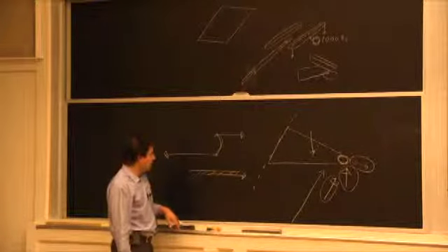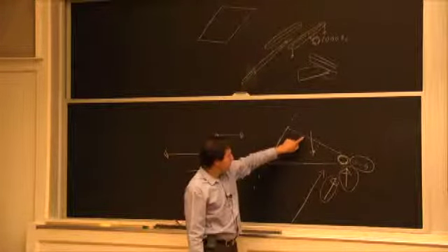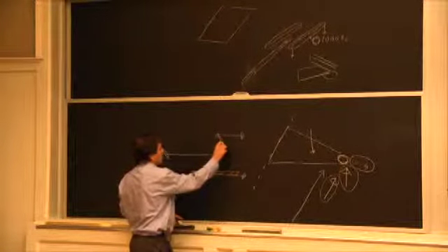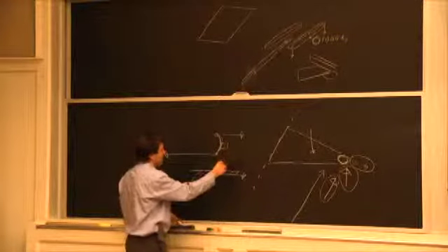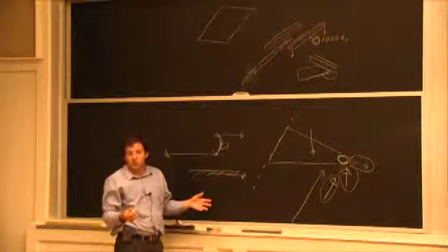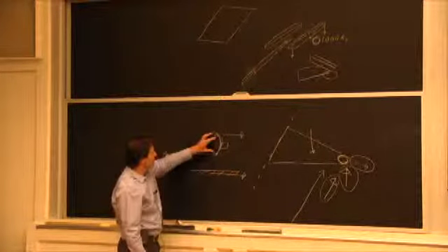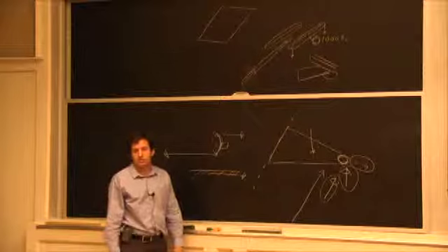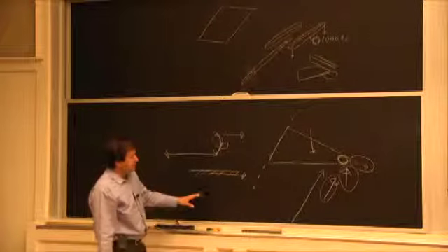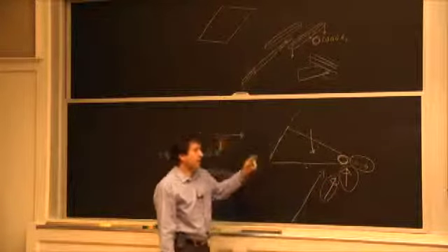And if I try to do the same for the size of this member as opposed to this member, I end up with similar characteristics. If I'm looking at that knuckle here, what I've seen lots of times is they make it stronger on this lower half. Sometimes it's just twice as wide, so you know exactly that it's stronger as opposed to this half, because they know that it's not going to have to resist the same loads. A combination of worst case scenario loads, field testing, and material testing.